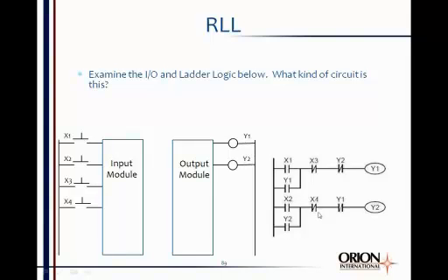As soon as I press X4, it opens up this normally closed contact in the relay ladder logic, which breaks the power flow to Y2, which opens up this auxiliary contact and closes back this normally closed contact. What is that circuit? It's exactly the same circuit as we looked at earlier in terms of a forward-reverse start-stop circuit. A forward-reverse motor starter circuit, in other words, right?